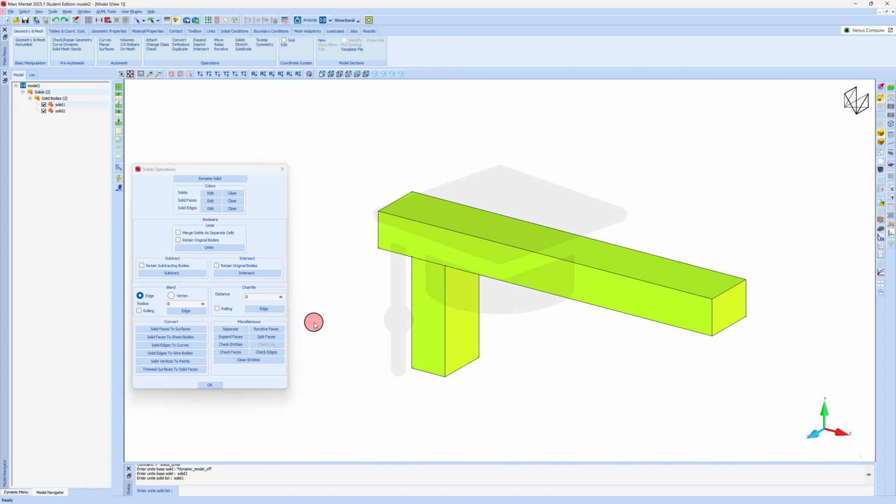Next, to complete my selection, the tutorial says that I have to push this button. And I think it's just worth mentioning what this button means and why it looks the way that it does. This button means end a list selection, and we often have to pick lots of lists of things in Marc and Mentat. If you are writing Mentat scripting code and you want to end a list, you write a #, just like is shown on this button. And actually, wherever you could push this button, if you were to type the # into this window and hit enter, the same thing would happen.